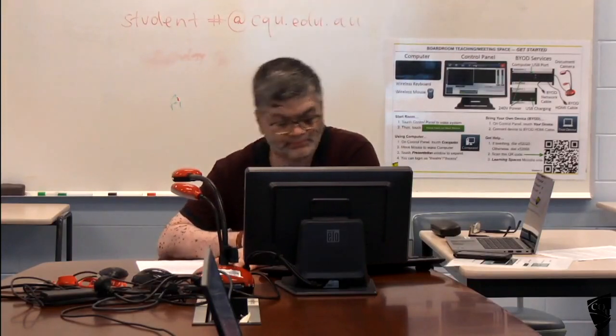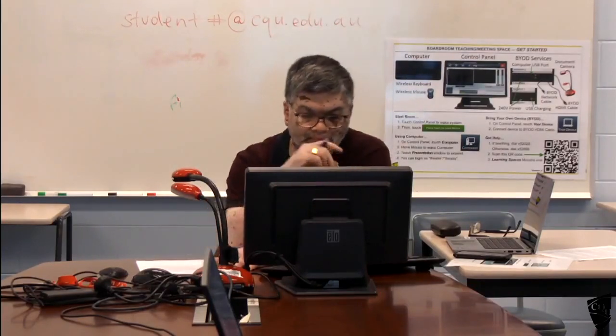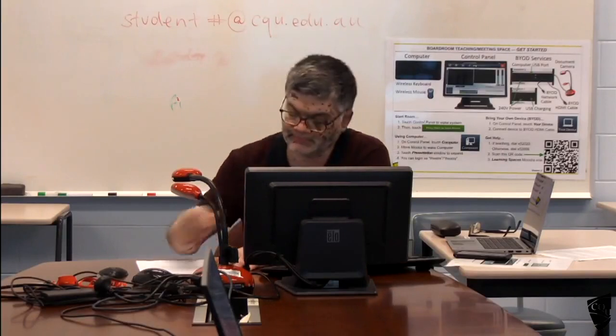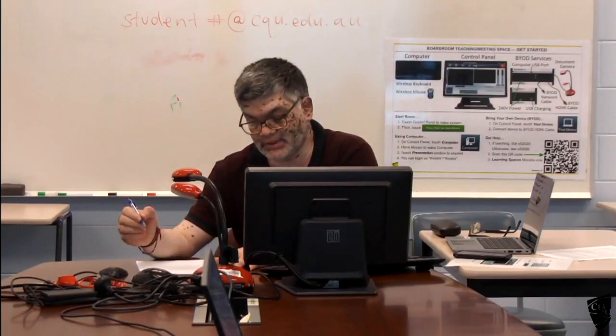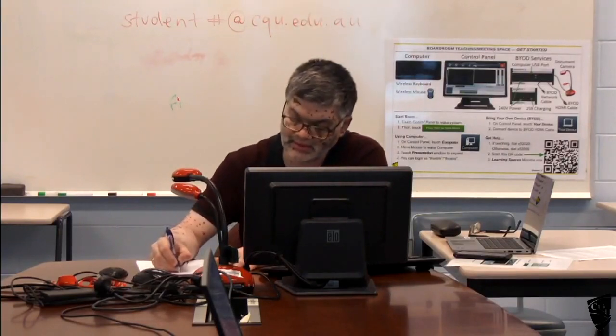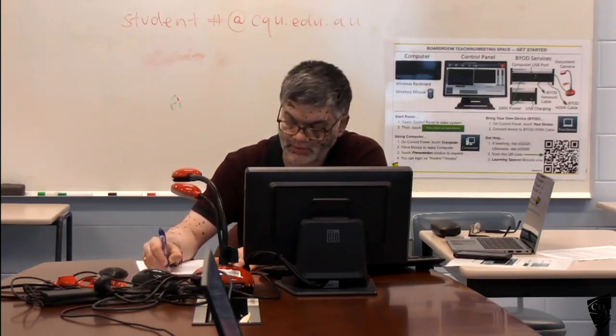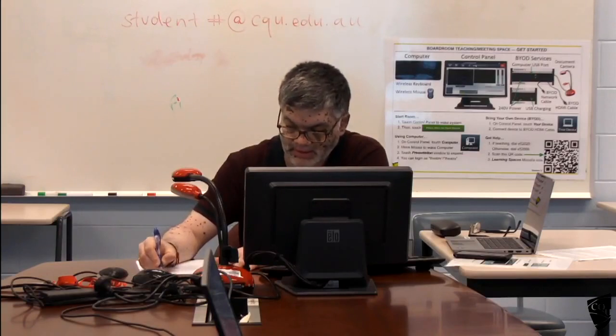Okay, so V star, normally V star is less than or equal to phi VUC. So in that case, no shear reinforcement is required.